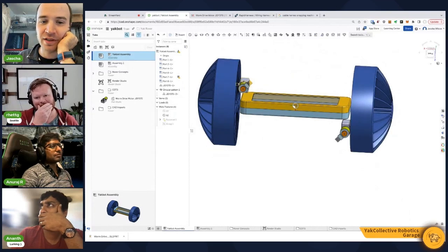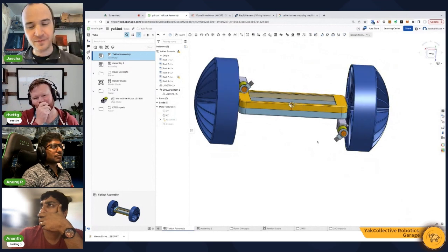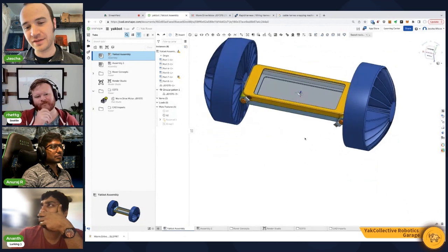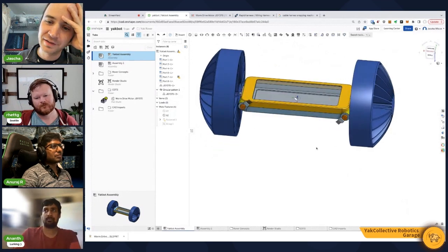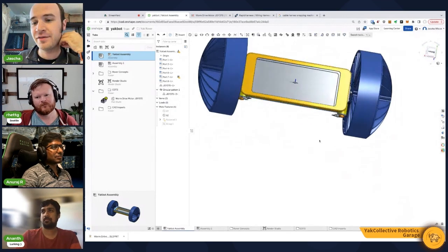Because what I would want is the motor to be up here. Oh, on the upper part. Yeah. So then you have to add the mate connector in the right spot, and it's a mess. But yes, the disambiguating: do you want a mirror of the geometry, or do you want to put the same part mirrored in the assembly area? All the different CAD packages have different ways of mediating that issue.